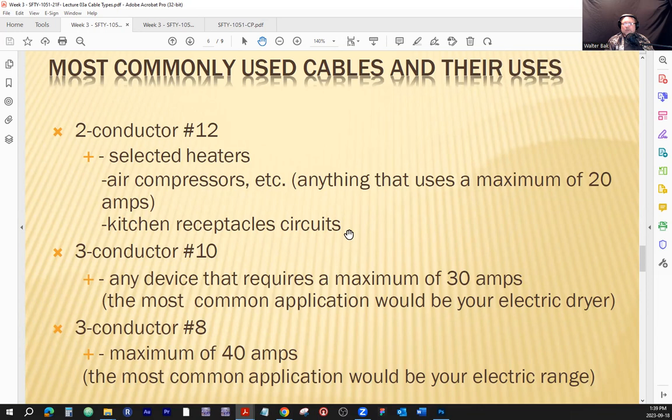So in that case, we are going to install split circuits. So the receptacle is not a duplex receptacle on one circuit, it's on two different circuits, and each is capable of providing 20 amps. This way, we don't overload the circuit. Now, mind you, it's not just enough to replace a circuit breaker with a bigger ampacity one at the electrical panel.